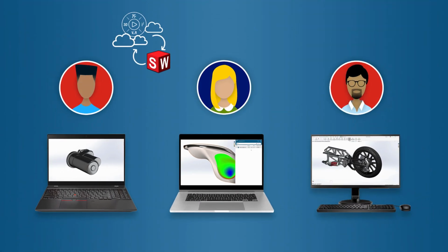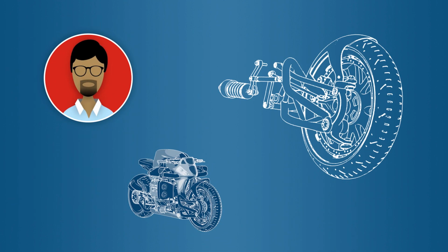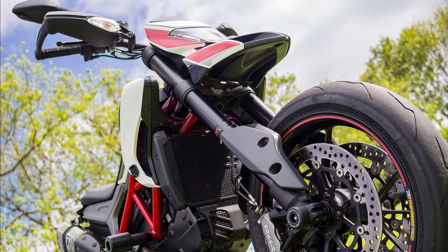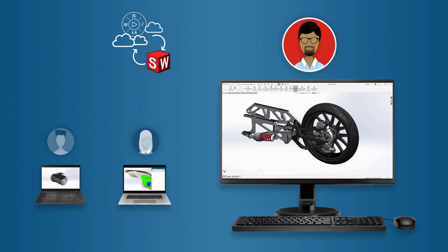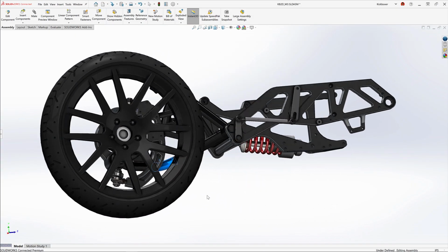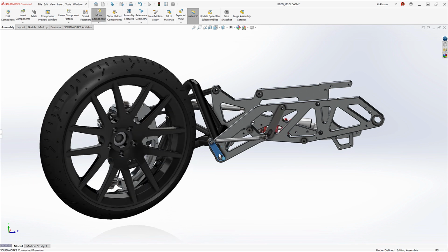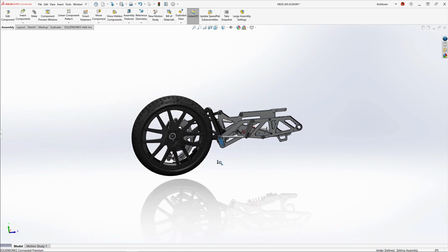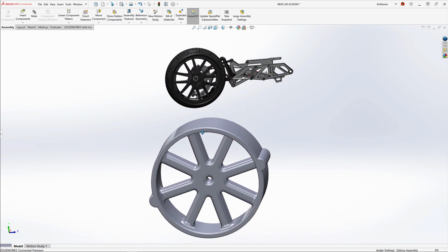While Debbie is designing the tank in X-Shape, Eric the engineer tackles some important suspension issues with the front end of the motorcycle. Instead of a traditional fixed fork and suspension, the KB2 uses an innovative swing arm and cable-driven steering system. This adds a ton of complexity to the front end design, so Eric created a virtual testing rig to understand how the front end will perform while riding over large bumps and steering the bike.